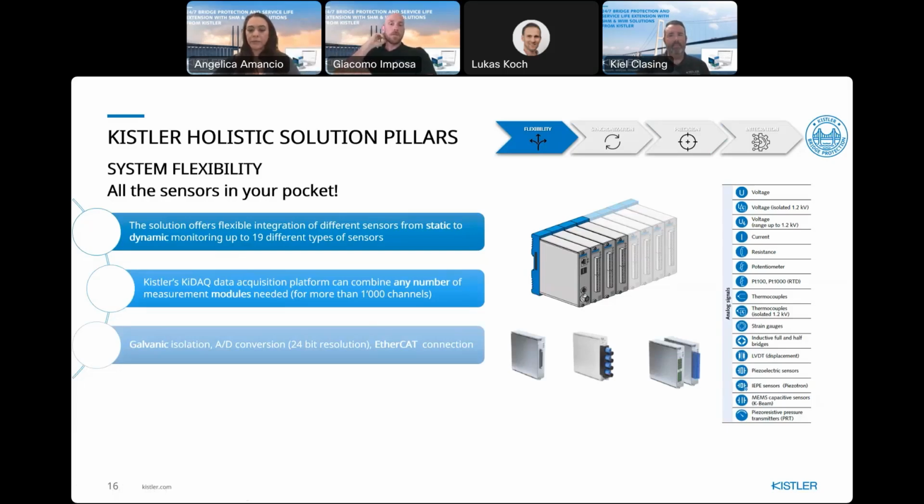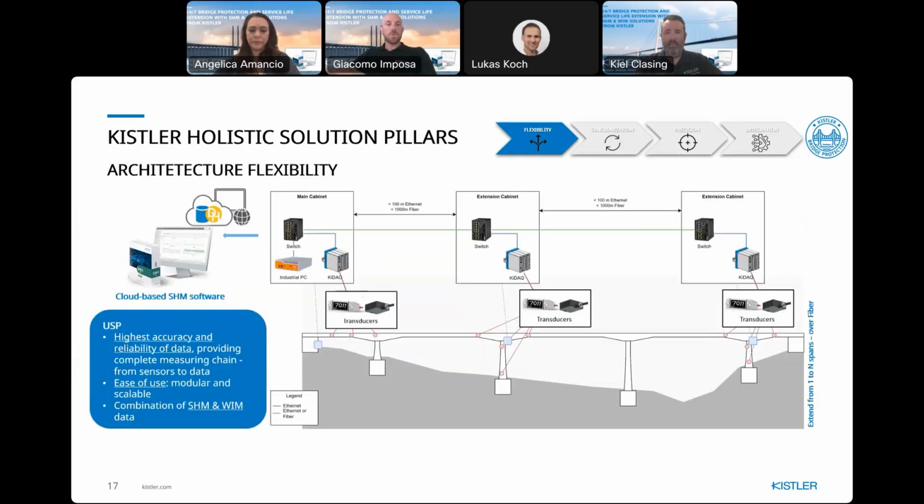Why? Because even if there are, as I explained, different types of measurements and different types of sensors, with our KiDAC, our data logger, we are able to collect any type of input, and it is also really portable and compact, and we can place it in different locations on the bridge. Among the specific requirements, it has galvanic isolation, analog to digital conversion with the most important value being 24-bit resolution, and IEPE connection. So this important tool defines the flexibility of the system.